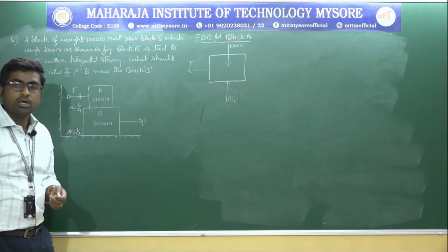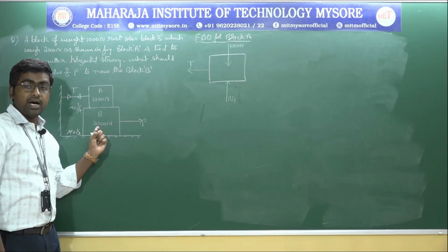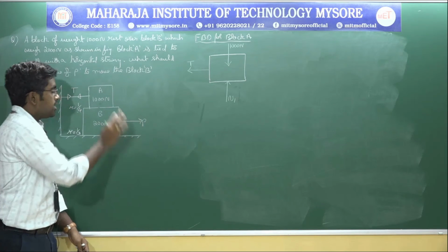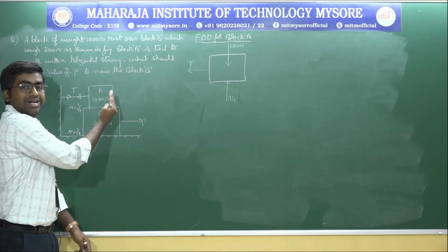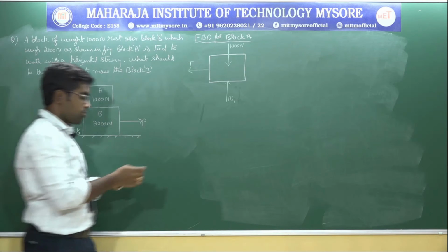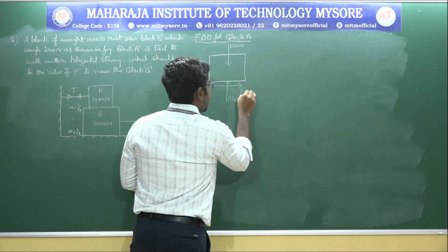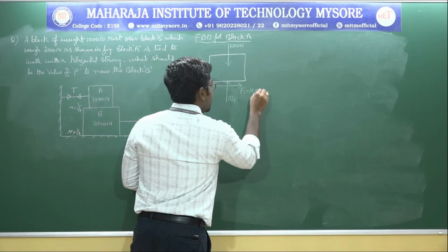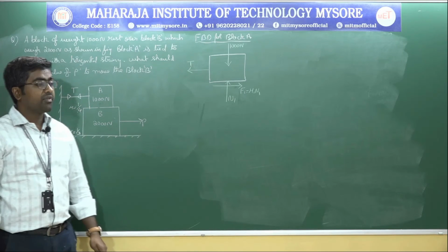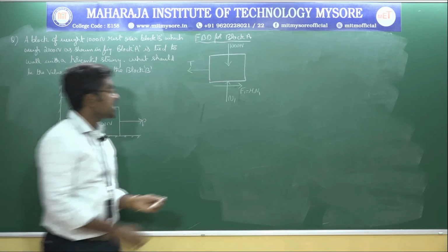So this will be the tension, and this is how I need to represent the tension, and this will be T. As I explained earlier, when you apply a force on block B, block B is going to move towards right, but block A will move towards left. Therefore, the friction will be opposite to the impending motion, and the friction will be acting like this. This will be F1 is equal to mu1 into N1. So this completes the free body diagram for block A, right?